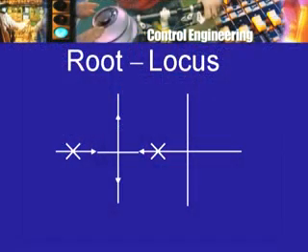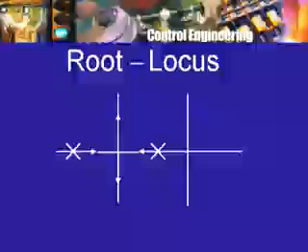some conclusions which one can draw from the root locus method almost immediately. Of course, with some practice, the same conclusions can be drawn using the Nyquist approach. For example, we had, let us say, to start with only two poles, no zero. So, what was going to be the nature of the root locus? Well, these two coming together, breaking away and going into the complex plane, no instability, but maybe oscillations beyond a certain value of the gain k.